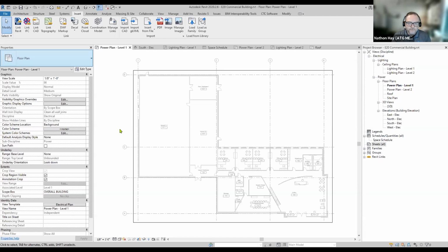They're called groups, but it'll be saved there and you can piece it together as you need, and it gets faster and faster, and you'll save that as a template project so that if you've got a typo in your general notes in this job, you don't copy that over to the next job. You go fix the typo in your template and then start fresh from there on your next project.